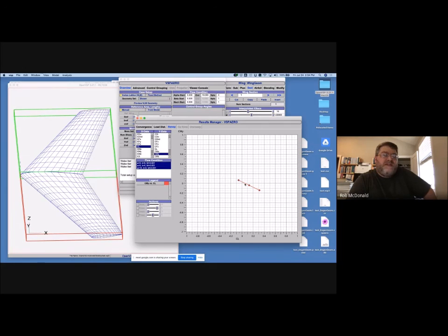Now, you have to satisfy, is that CL the CL you want it to be? And so what you do is you look at that CL and you look at the weight of your airplane. And of course, CL of the airplane is weight divided by QS, Q being the dynamic pressure. So weight divided by 1/2 rho V squared times the wing area S. And the important part of that is the V squared, right? There's a velocity in there.